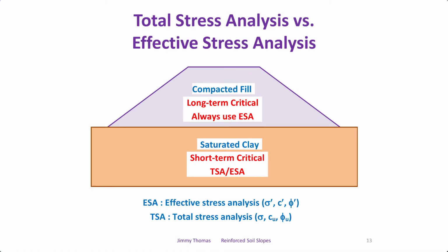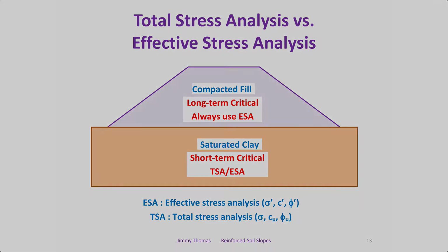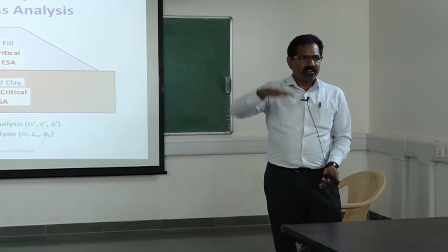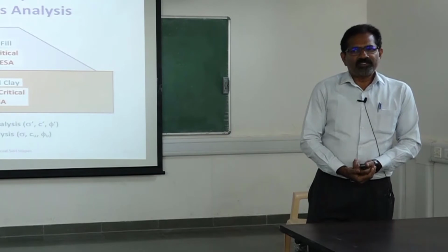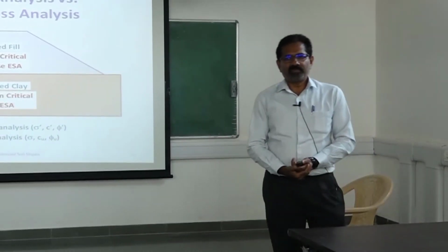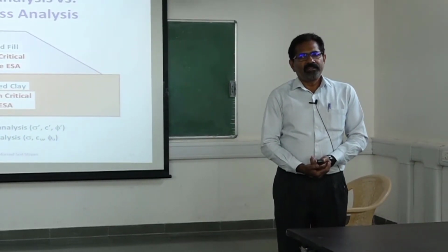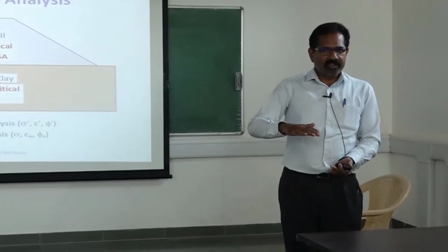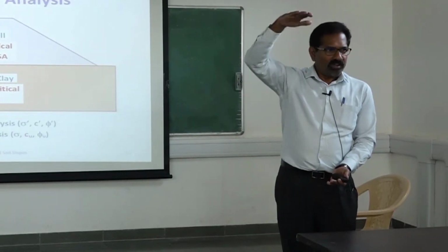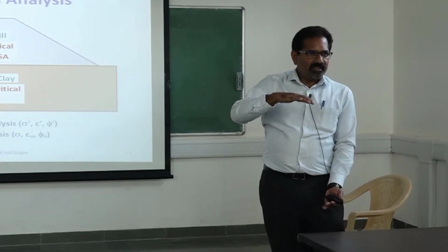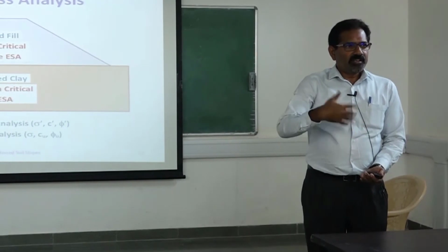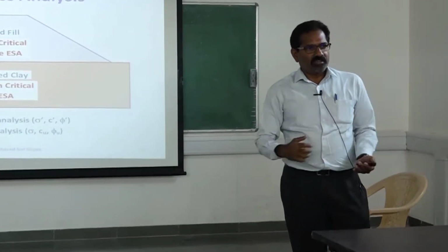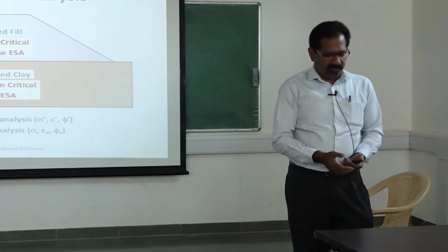Now, when you do a stability analysis, sometimes we look at long term, short term. Like if I am making a building, the foundation, which is more critical, when is the factor of safety lowest? That means what we call the end of construction. As soon as I construct the building, the full load I have applied, the soil stresses have increased, but then the soil has to consolidate. Then with time, the excess pore pressure dissipates, the effective stress increases, factor of safety increases, like that.